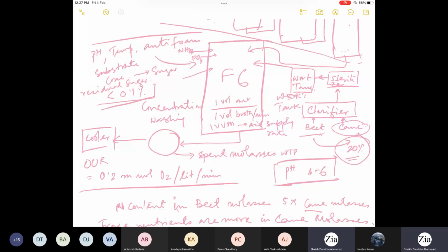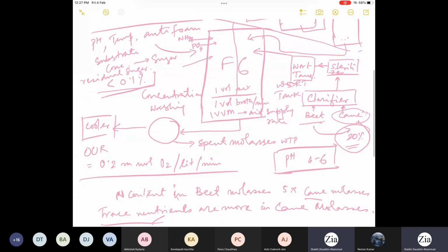And in the large fermenter, the air supply will ensure good mixing and also provide oxygen, and you may have a stirrer inside the reactor as well. Whenever you have mixing using a stirrer as well as aeration, due to abrasion you will have cell disruption.